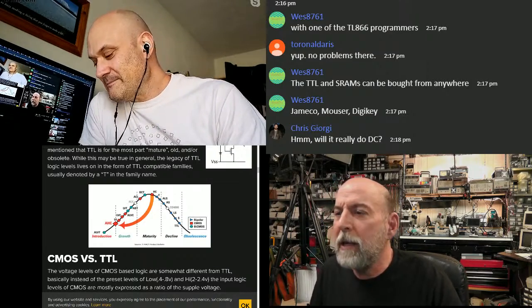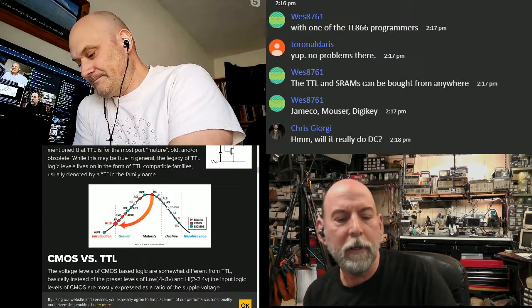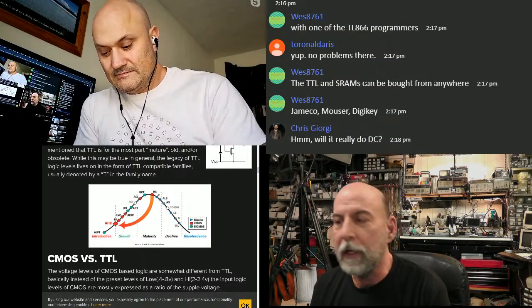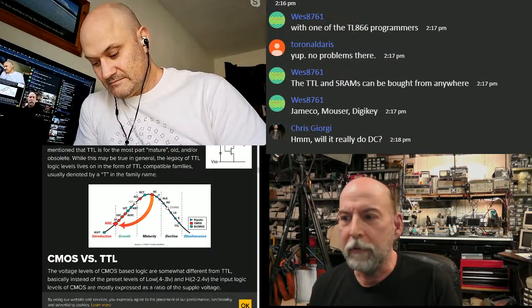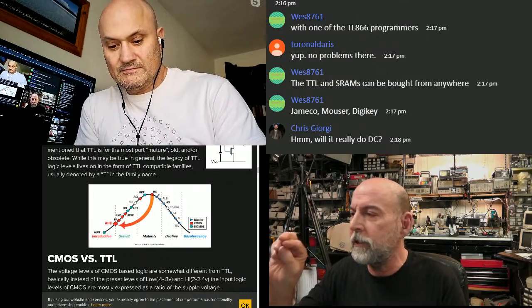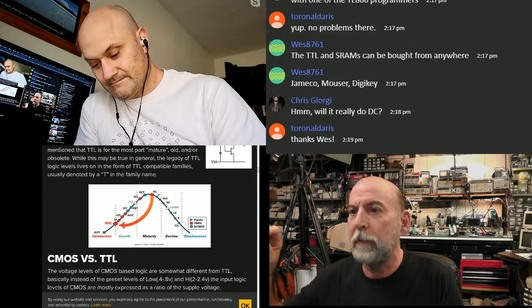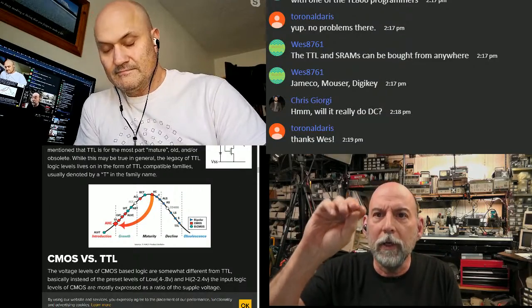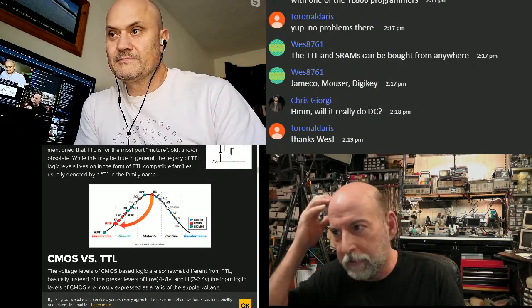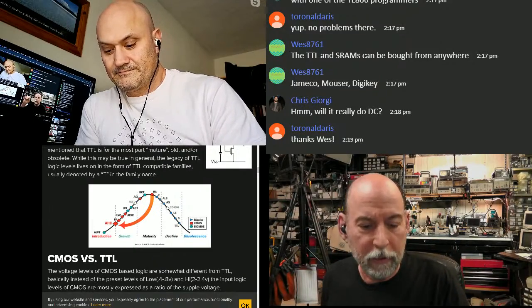Yeah. And the companding you were talking about, there's companders for VoIP. That's big these days. And like mu-law. And it's based on the human ear. We hear really articulately on the fast moving part of the signal, but where the signal slows down, it's not as accurate. And so it feeds the ear what it wants to hear.